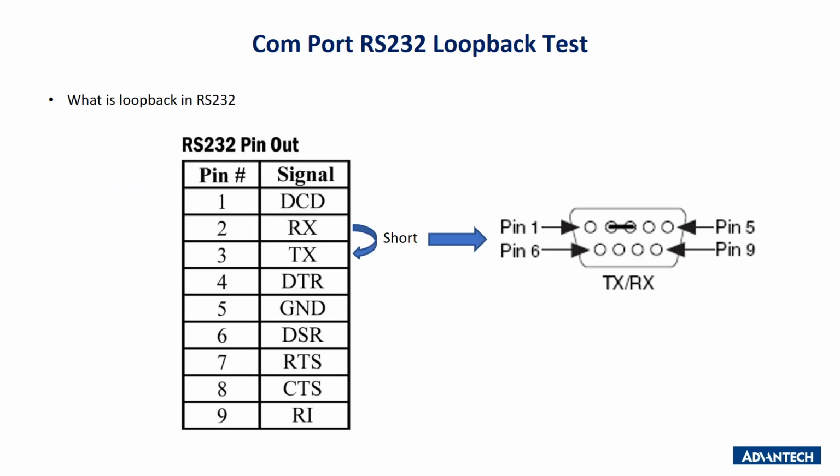Loopback test is a typical method to detect if the COM port is good to go. Please make sure to do a loopback test before you start to work with it. The basic concept is to connect its own TX and RX pins. Once you open the COM port and then send the command, you would also receive the same message as what you sent.